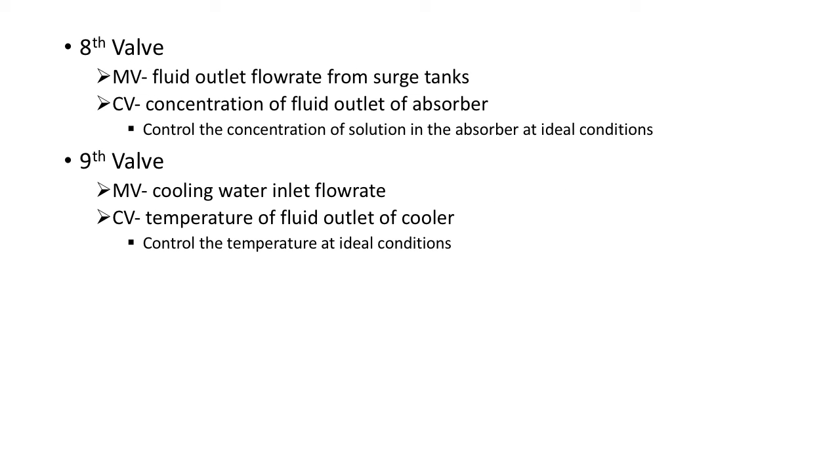The 8th valve is used to control the concentration of the solution coming out from the absorber. The manipulated variable is the outlet flow rate from the surge tank. This is to control the concentration of the solution at ideal conditions.